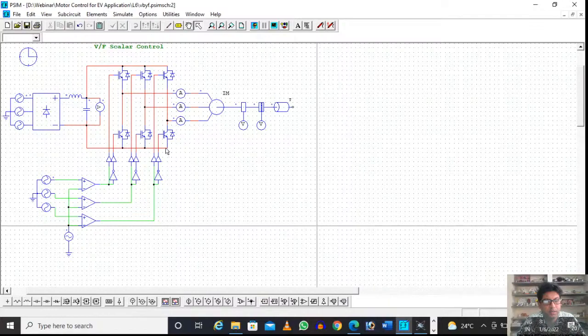This is a 3-phase 2-level inverter, you all know. Each phase has two switches, one upper and one lower. Both are complementary switches. That means if both switches are on together, it will create a short. The DC will be directly shorted through that path, and very high current will flow, which will damage the junction of the semiconductor device. So whatever pulse I give to the top switch, you see I have this NOT gate, I have inverted it and given it to the bottom switch.